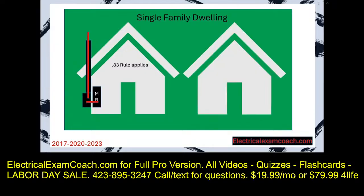Now let's imagine that we have a main breaker outside, we have the service riser, and we have a main sub-panel inside. We have the riser wire and the wire going inside. The 83% rule applies to all this wire. You can apply it to the wire going up the riser, and you can apply it from the meter disconnect combo to the first main sub-panel.